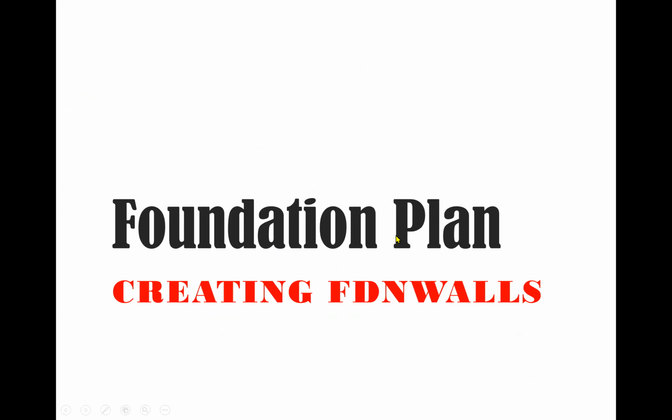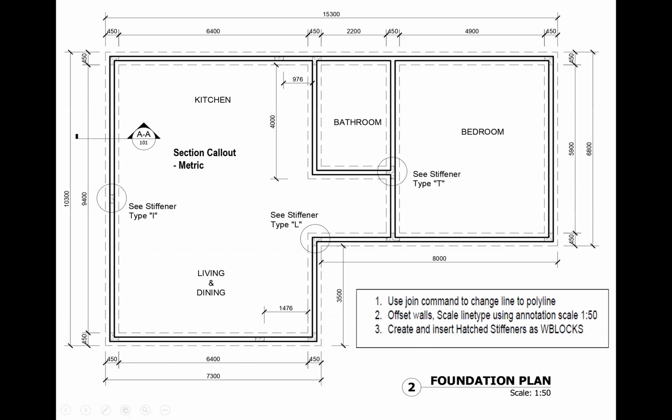So I would have given you a definition for the floor plan. So I'm now giving you a definition for the foundation plan. While the floor plan was a horizontal section going through the building above window sill, your foundation plan is also a horizontal section going through the building, but this time it's happening below the level of floor. So if you cut through the building below floor, then you can't tell where your door openings are. You can't tell where your window openings are because the walls are just coming out of the ground. So you're cutting the wall across.